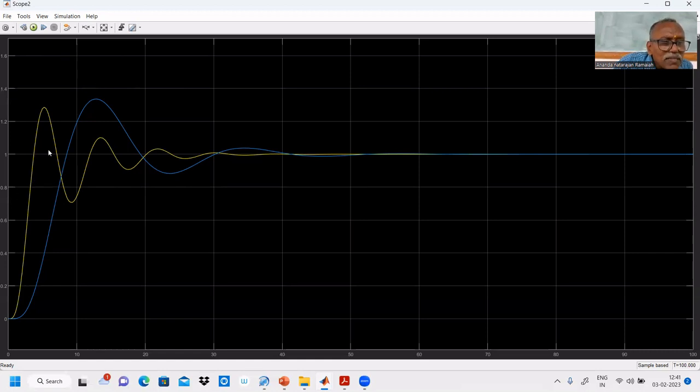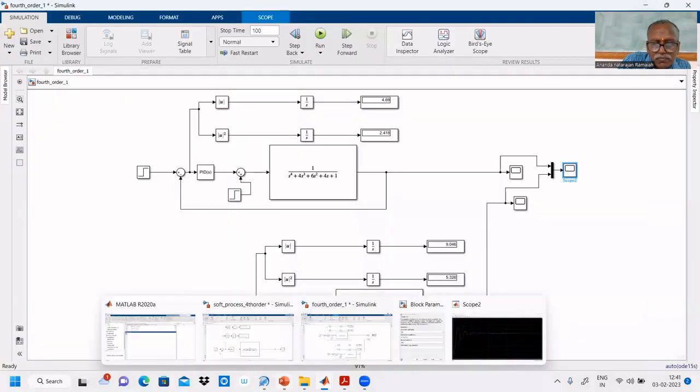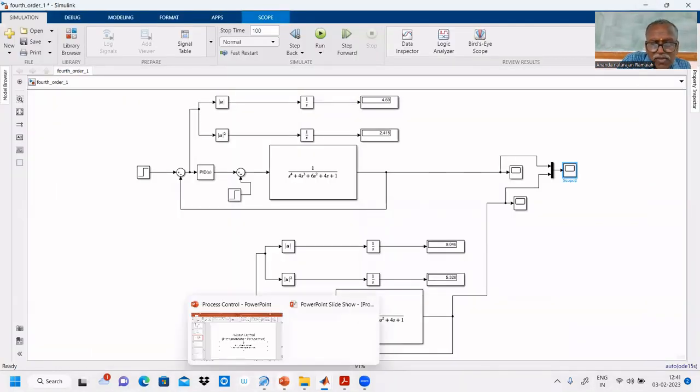But anyhow, the sluggishness is there. That is not changing. So to make the system smart, we are including proportional mode. If you use proportional only mode, it is smart. Then can we remove integral mode? If you use P only mode, there will be a steady state error. That's why we are using P as well as I mode. What are the other drawbacks with integral mode?